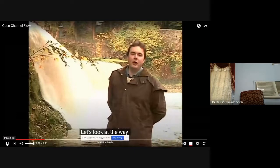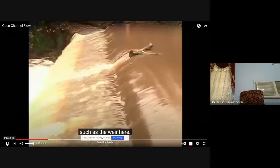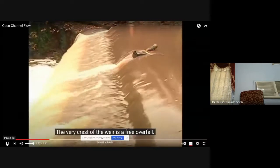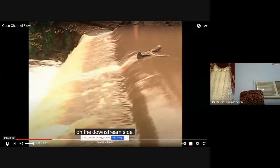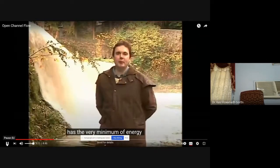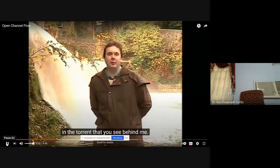Let's look at the way the water negotiates obstacles such as the weir here. The very crest of the weir is a free overfall. There's no resistance to the flow on the downstream side. So as soon as the water has the very minimum of energy it needs to pass the weir, it plunges over in the torrent that you see behind me.